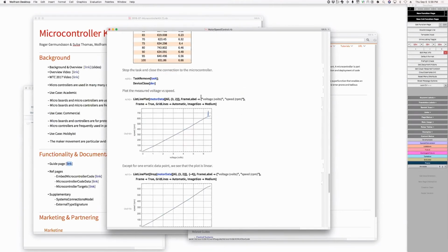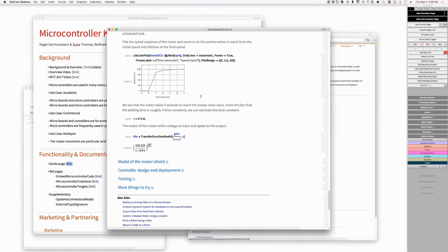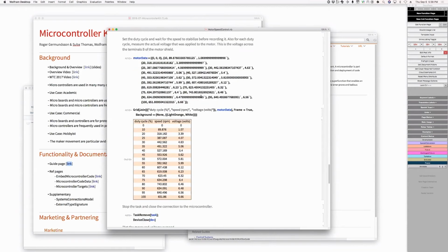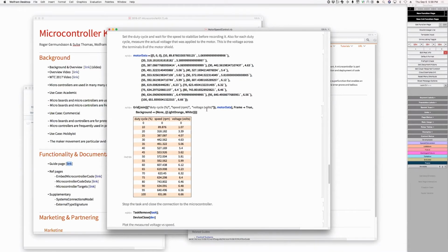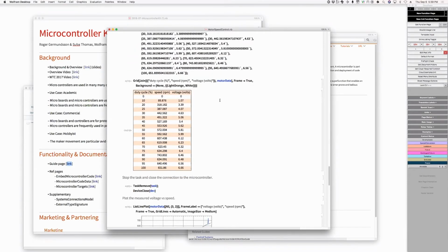But Stephen, coming back to your question, doing it using some port or something is more complicated than this, because we are reading very high voltages and the microcontroller cannot read that. See, I'm getting 6 volts and so on. The microcontroller will max out at 5 volts. Then put a resistor there or something, or use a different motor. I mean, I don't know. Put a resistor, split the voltage. I mean, the idea that you're by hand reading a voltage here sort of spoils the point of this.